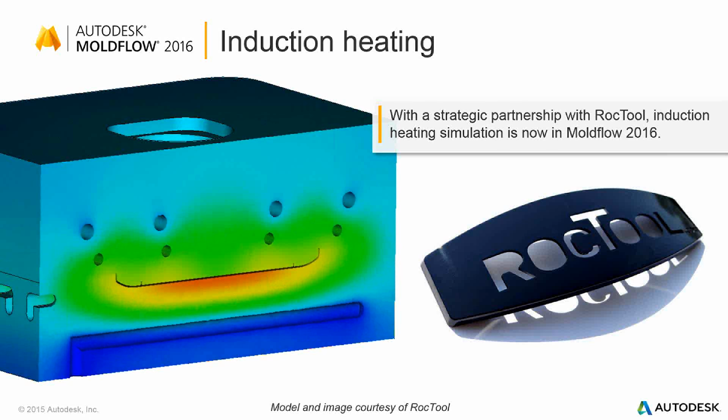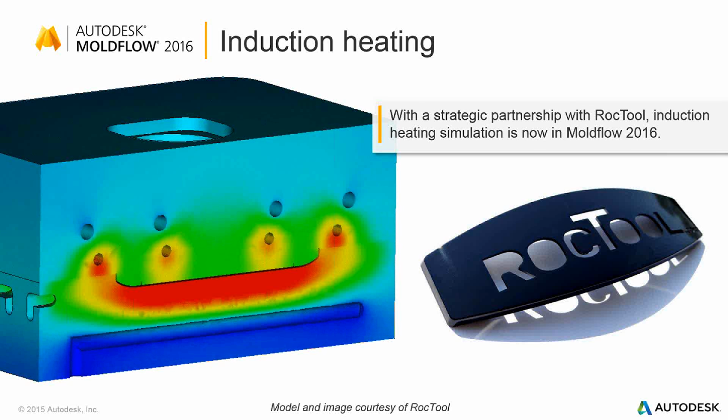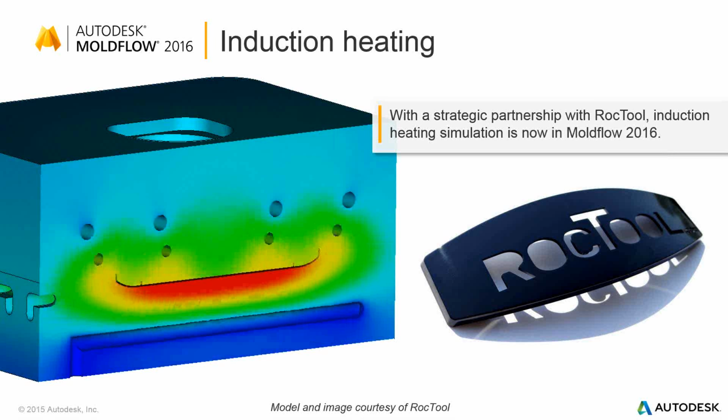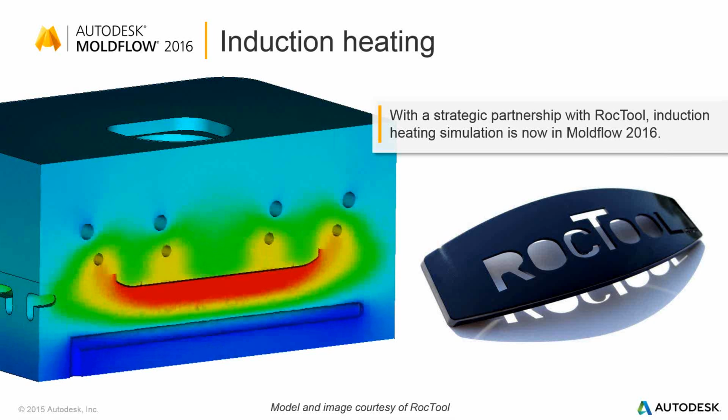The other benefit of the Rocktool technology, or the induction heating technology, is that the temperatures you can achieve with this are much higher than you can with, for instance, steam heating or heating cartridges. The company that brings it to market is a company in France called Rocktool, and they have started making really good inroads in the United States as well. They had a really good exhibition at the NPE, where I think two or three places were showing their technology live on the floor.